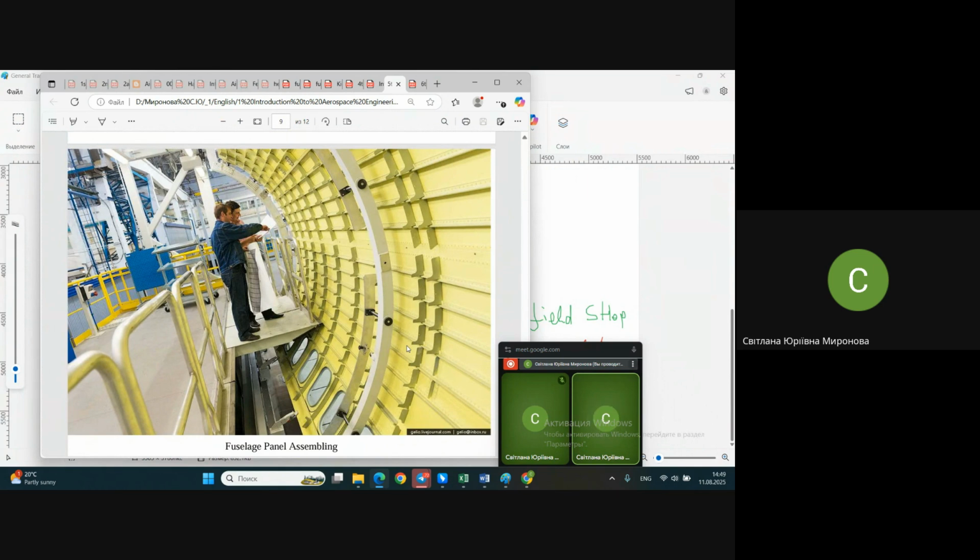What does it mean to remove the human from this technological chain? Preferable will be automatic or even robotic riveting, in case you have money for robots. No, let it be at least automated one by using the presses. Press will give you uniform force each time. Press may do more than one rivet for one stroke, so-called group riveting, and so on. And moreover, press gives better quality in terms of the future fatigue life of this place, of this rivet, because of better tightening of the rivet in the hole. So automated riveting is preferred.